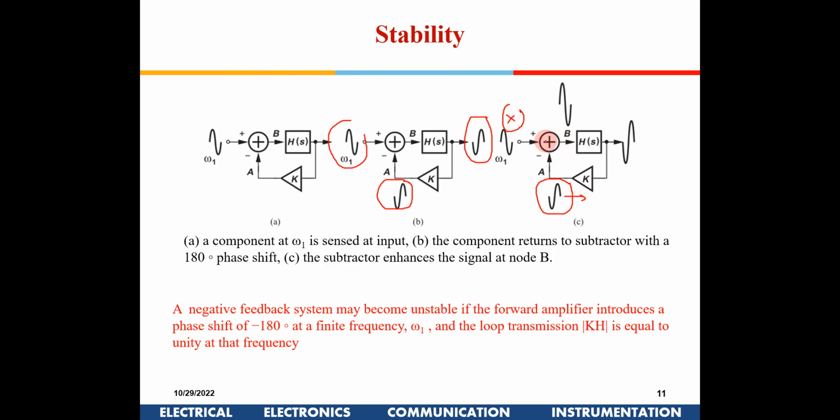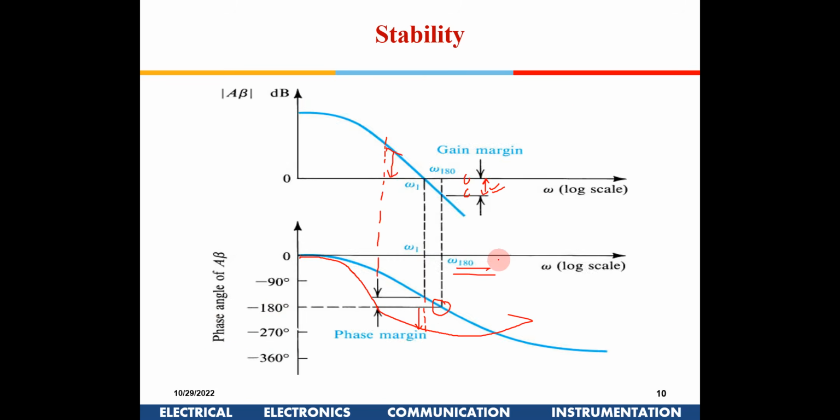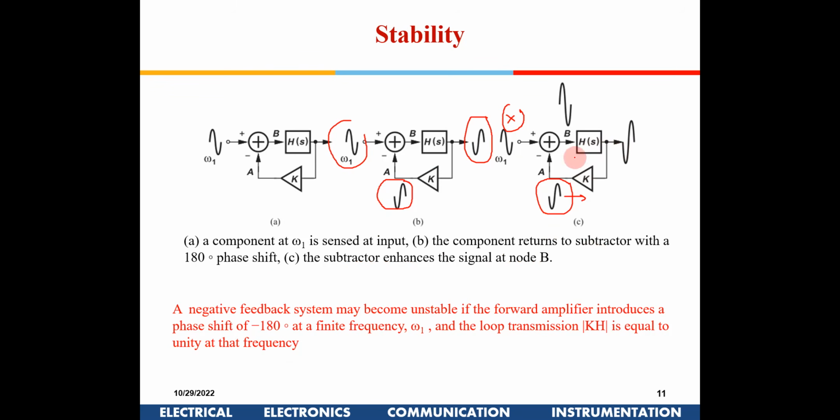You just interconnect this. If you interconnect this in the frequency band, if I go here, right, there will be noise in all the frequencies, right? There will be noise always, some small amount of noise across all the band. You can't avoid that. That will be there in the atmosphere in these devices. So a small noise, what would happen? It will come here, it will come here, it will come here. Okay, 180-degree phase shift again, and the gain is more than 1, so it will get amplified here.